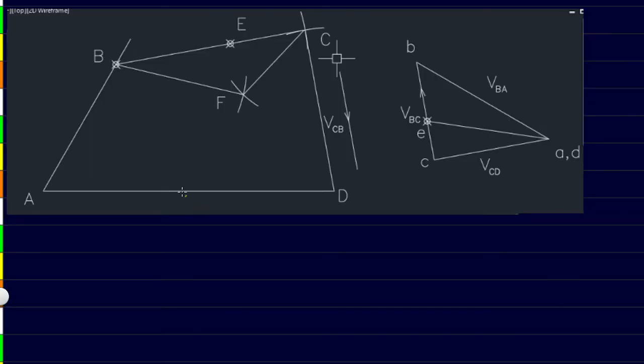Okay, so we'll be using the length ratios here in order to build a similar triangle over here. We already know the length BC, and that is 66. We already know the length BF, and that is 45. Now we need to use the comparison here for the velocity diagram. So we also have built the length of small bc.